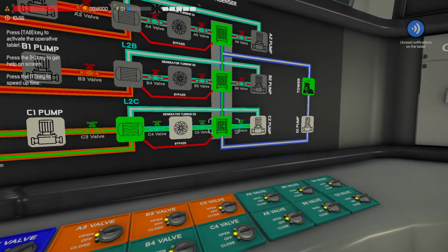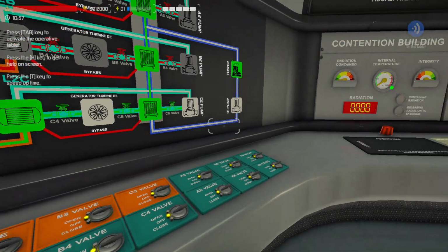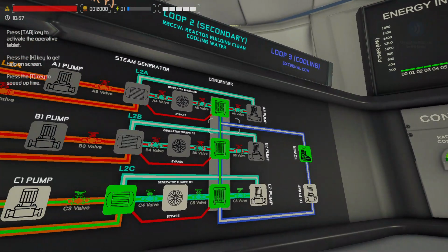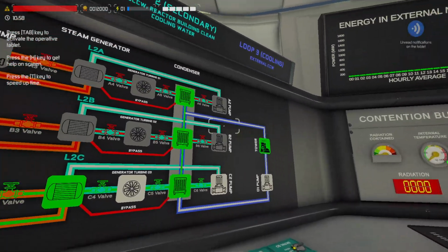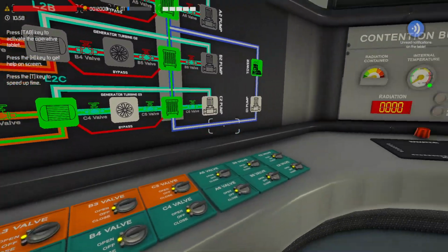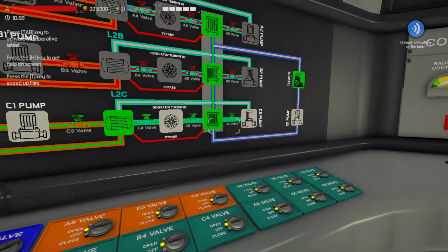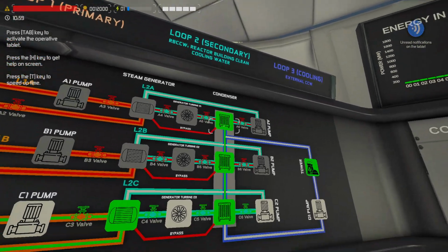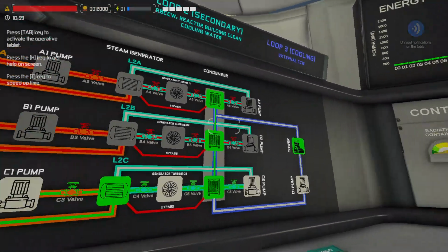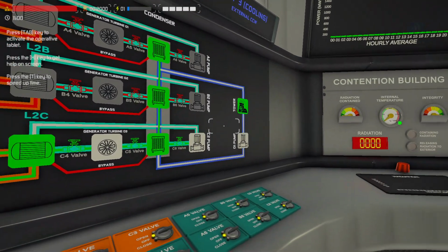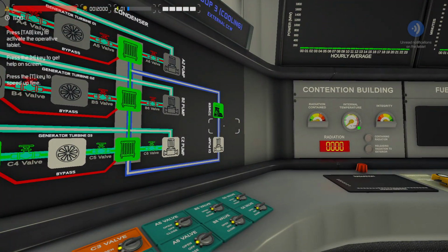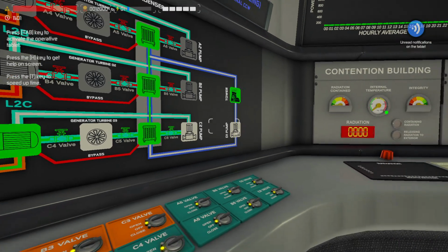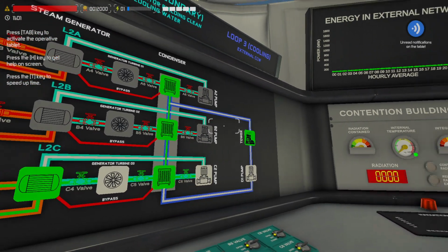And then what's actually cooling down this condenser is this cooling water loop. So your tower, your condenser pump, and then it would go through, take heat from all these. I would imagine there would be a pump that goes to this and then comes back, this comes back, this comes back. So one pump going to all 3 condensers, so it's going to have a massive flow rate. And that's the other side.